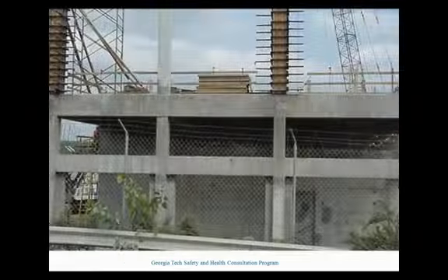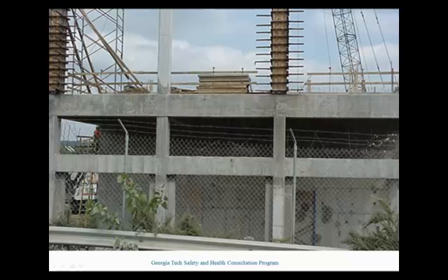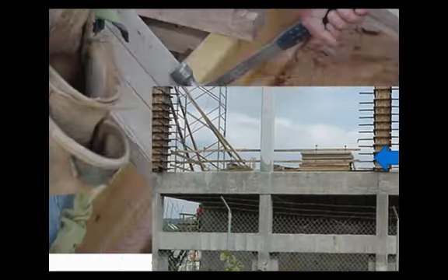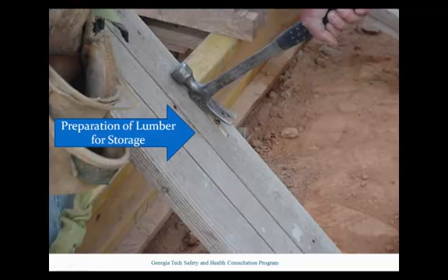For materials stored inside buildings under construction, they should not be placed within 6 feet of any hoistway or inside floor openings, nor within 10 feet of an exterior wall which does not extend above the top of the material stored. When storing used lumber, all nails must be withdrawn before stacking. Also, lumber must be stacked on level support pads so that it remains in a stable position.